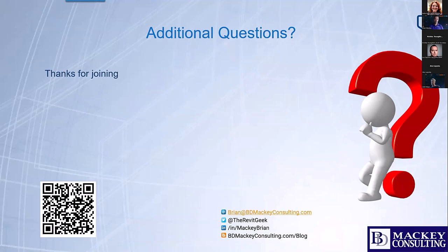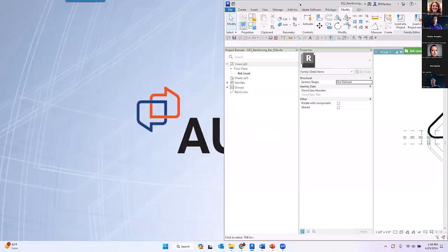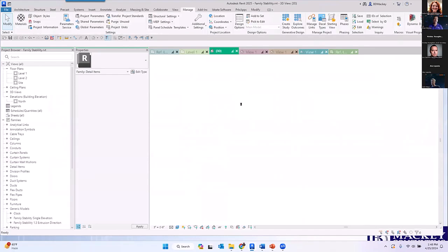How to standardize a family which I created so it can be converted into an IFC format? Well, unfortunately, in the Revit world, we can't export families directly to IFC, at least not to my knowledge. And I will be the first to admit I don't do a whole lot with IFC. But I don't believe there's any way to export a family to IFC natively.